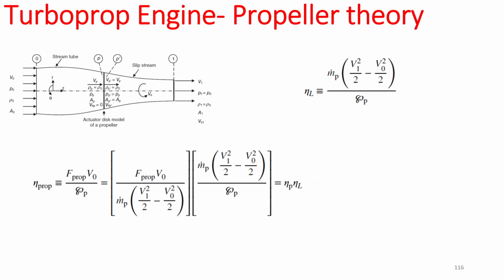Okay, so that's it for the momentum theory of the propeller. Let's talk a little bit about the blade element theory. As mentioned, blade element theory is a little more complex, but it deals more with aerodynamics and airfoil theory. So it essentially follows the classical airfoil theory, and it says a propeller is a spinning or twisted wing with an angular speed of 2 pi n with a span-wise element in solid body rotation. So we are essentially assuming that each blade is a wing that is rotating, right?